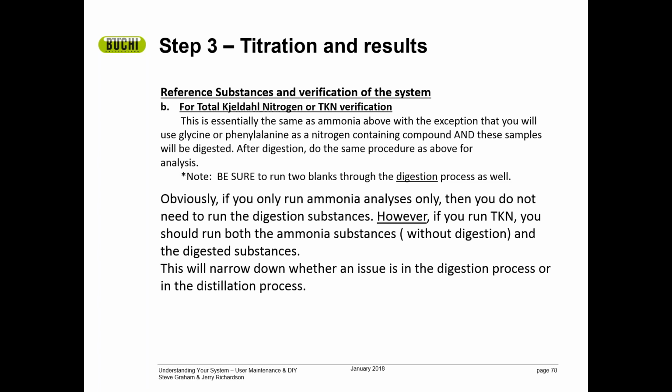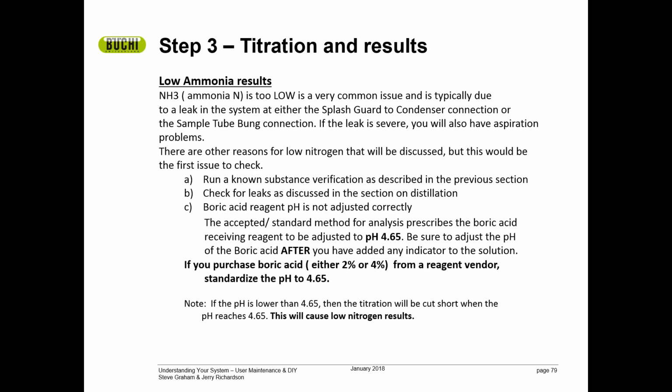Because if you're using a TKN solution in your analysis, we need to look at whether the digestion process is working correctly. If the digestion process is working correctly, is the titration process working correctly? So it's very important that we can narrow down an issue using two different verification substances.